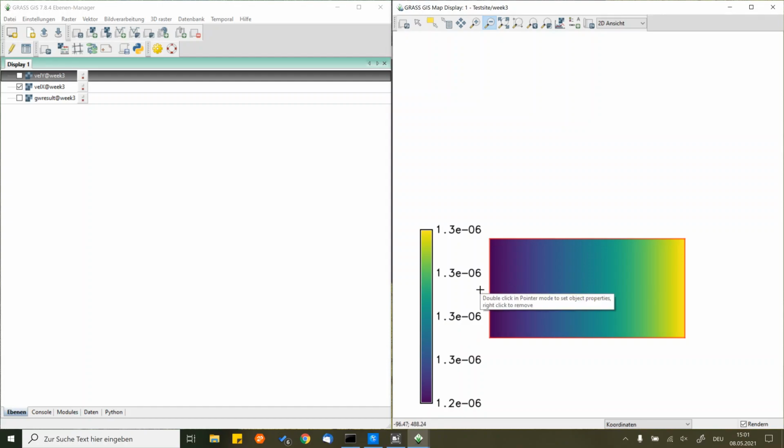So we assume we have a pressure gradient from left to right because the pressure gradient is 1 meter over the 2,000 meters distance. And then based on the hydraulic conductivity, we should have some flow velocity, which is okay. But what theoretically we would expect is having a linear pressure drop from left to right, which means a constant pressure gradient, which means we should have the same velocity from left to right. But why do we see such a gradient?